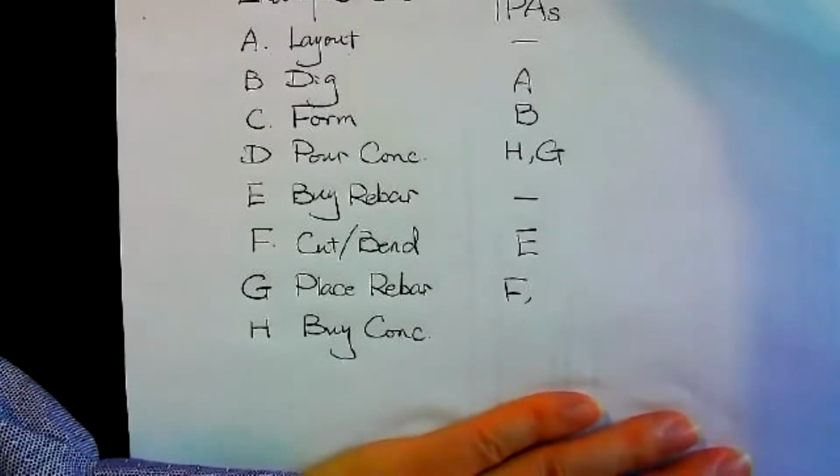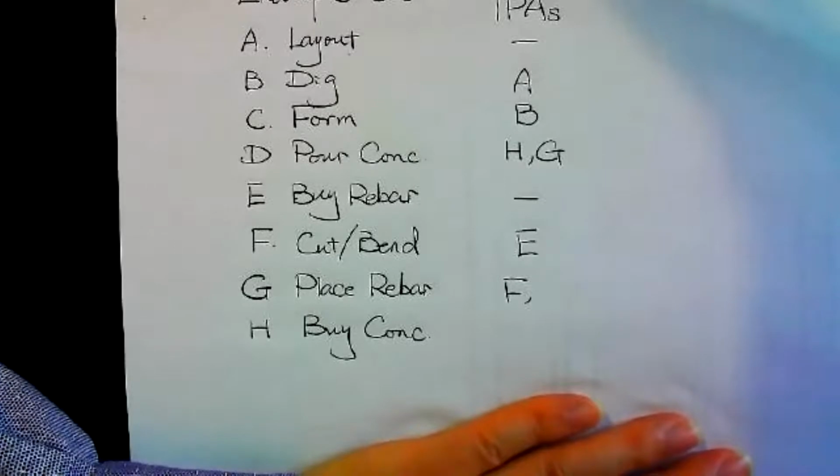What needs to be done before placing the rebar? The hole is ready, you want to place the rebar, or the form is ready, you want to place rebar? This is the question. Very good, very good. It should be form. It should be form.